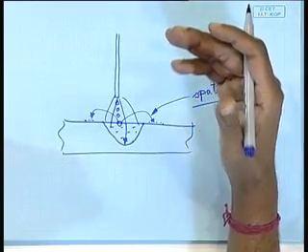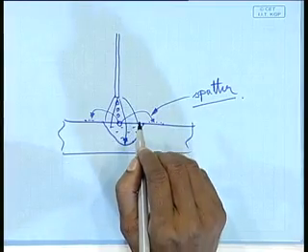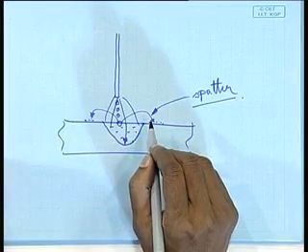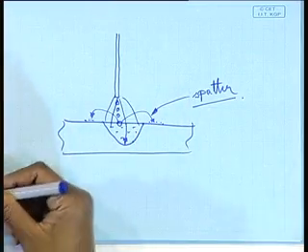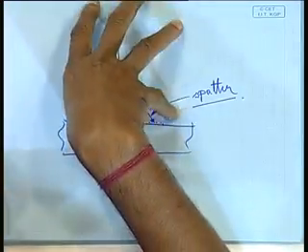So, that means to achieve a finer control on the deposition pattern and the fusion pattern, you will have to take the cumulative effect of all the welding variables. One of the welding variables is the flux, the shielding medium: what kind of shielding medium, what properties it has. That also affects the deposition rate, the deposition pattern, and the fusion pattern.